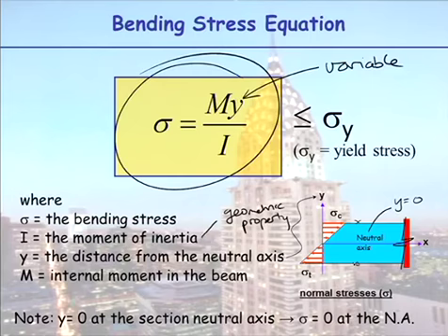You would draw a bending moment diagram to work out where your moment was maximum, and then you would know it was at the top and the bottom of the beam. So you couldn't just say in the middle of the beam. My moment is maximum in the middle of the beam when I push down with my chin and look like an idiot, yeah? My moment's maximum in the middle, and the bending stress is maximum in the middle, at the top and the bottom.